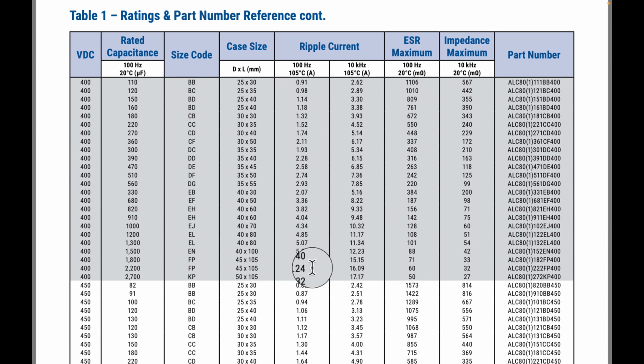Well, if you got 50 amps or something and you got 7 amps here, then you're going to need 7 of them minimum. And you want to go always above. You don't want to operate at max. So you're probably going to need 8 of these guys.